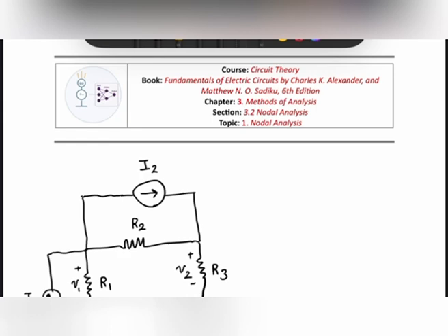What is nodal analysis? Nodal analysis is a technique based on KCL, which states that the algebraic sum of all currents entering a node is zero. Rather than solving for every current in a circuit, nodal analysis focuses on solving for node voltages, which often simplifies the math.